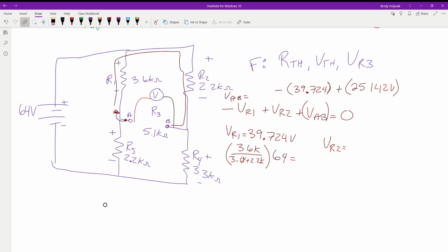With this one, we have more or less resistance total. A little bit less, so that's going to have a little bit more of a share. We lost it off of this guy. So what we should see is a value slightly higher than that when we actually look at this guy. But that was a good way to infer from that. So we're going to find it the same way. So 2.2K divided by the 2.2K plus the 3.3K, multiplied by the 64, and that gives us 25.6.